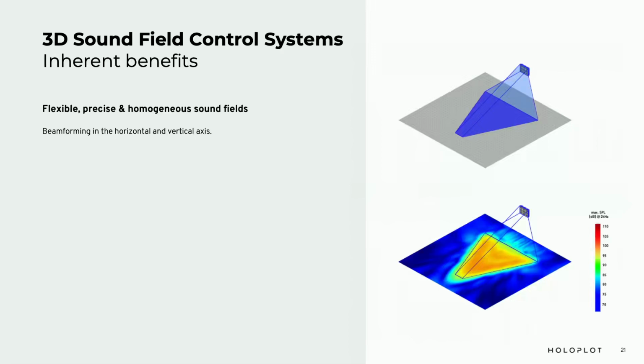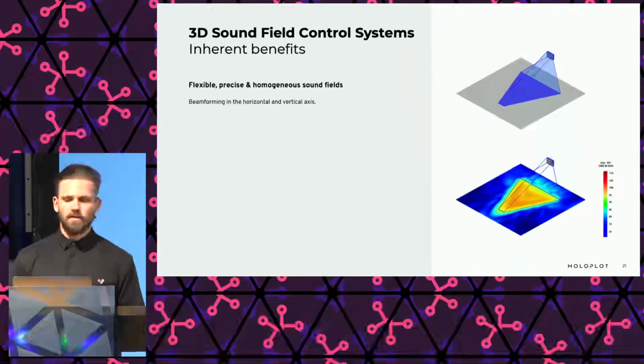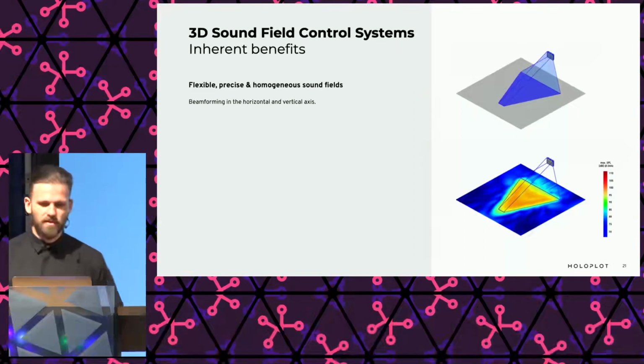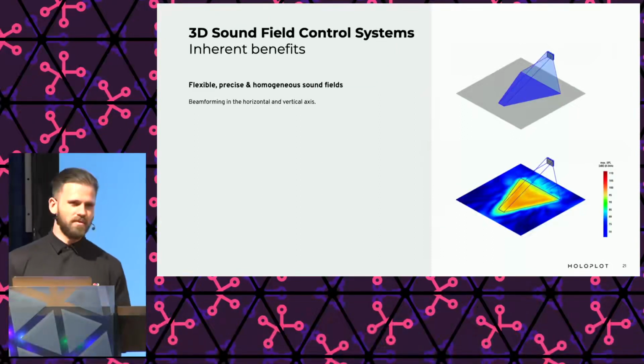In the beamforming that we are visualizing on these plots, the beam is actually converging at the far distances, also increasing the level, and at the closer distances, the opening angle is quite wide, and the level has to be accordingly reduced. So this is, as I mentioned before, doing exactly the opposite of what is expected of a loudspeaker.